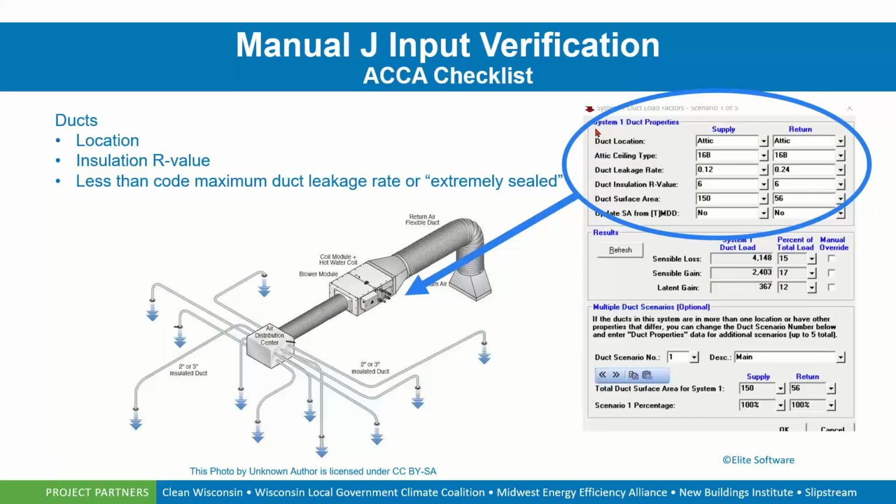We can also apply our duct location. So in this slide, we see that on the right-hand side, the software is asking us for a duct location. It can be in an attic, it can be an unconditioned basement, it can be within a floor system, an exterior wall, within conditioned space, buried below the attic insulation. We assign the building component. In this case, a designation 16B just means, with the software, that it's an R30 ceiling insulation.